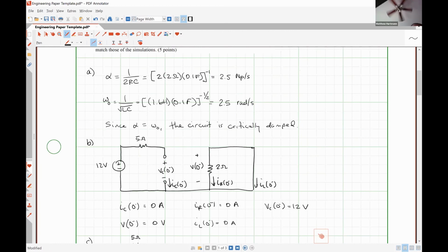So that's correct, because since there's no current flowing through the 5 ohm resistor because it's not part of a closed current carrying path, the voltage drop over the 5 ohm resistor is 0. So a simple KVL loop, sorry.